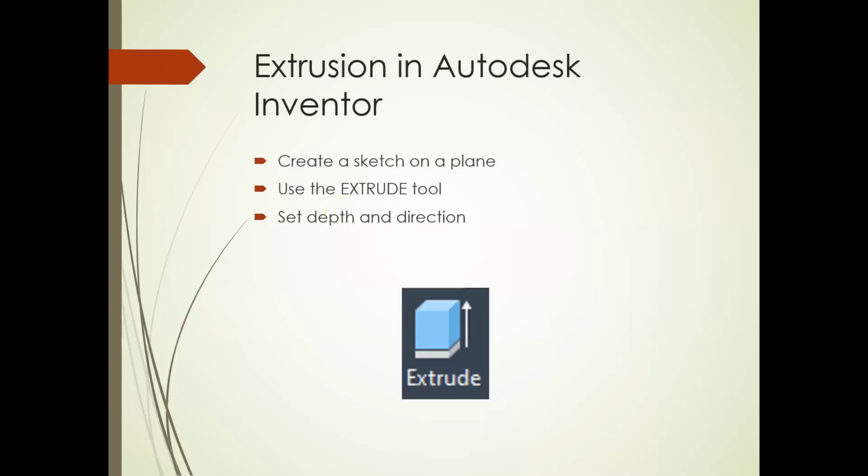Another thing that we're about to take a look at here in Inventor is going to be the extrude command, right? So we're going to extrude something. We're going to set a height and a depth, and once again, this is going to work exactly like how it did in AutoCAD, and we'll also be able to give it a tapered angle, right? So the same function is going to apply throughout any solid modeling program, right?